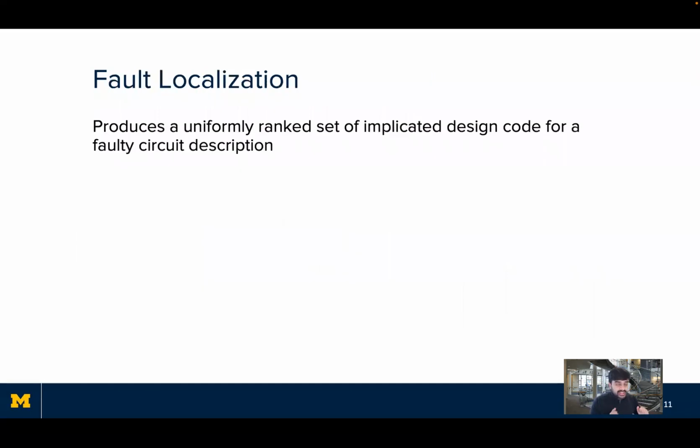All right. So let's now shift gears and talk about addressing the second problem highlighted at the beginning of my talk, fault localization. As I mentioned earlier, traditional fault localization approaches from software APR are rendered inapplicable to these hardware descriptions that are parallel in nature. This is where novel fault localization for hardware designs comes in. At a high level, the CirFix fault localization approach produces a uniformly ranked set of implicated design code for a faulty circuit. Our approach starts with the abstract syntax tree for the circuit design, the output from simulating the circuit, and a developer-provided oracle for expected circuit behavior.